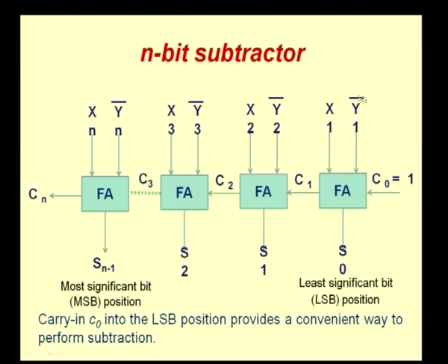Okay. So, the 1's complement you can see is just obtained by inverting each individual bit, right. So, if I have bits here y1, y2, y3 etc. up to yn, I have to invert these bits. So, if I say the complement of this, y1 bar, y2 bar, y3 bar and yn bar, these become the inverted values of the y's, and I also need to add a 1 to it, remember. Now, that 1 I will add by feeding it through this carry input that I have over here.